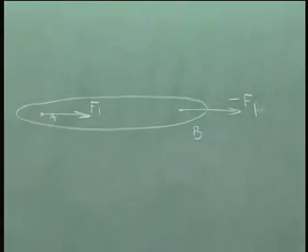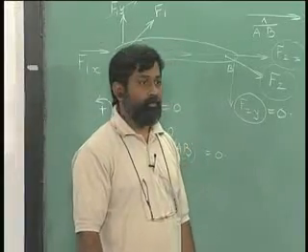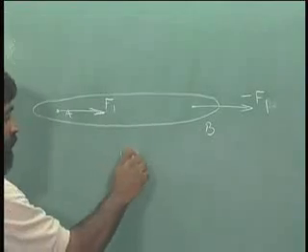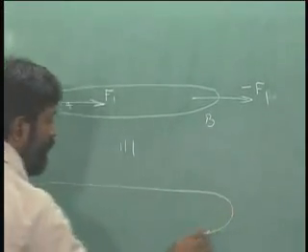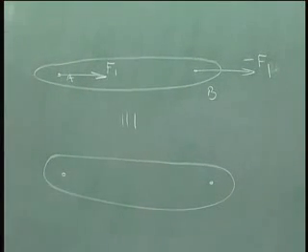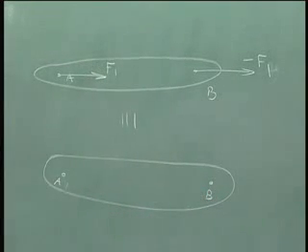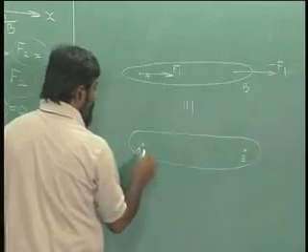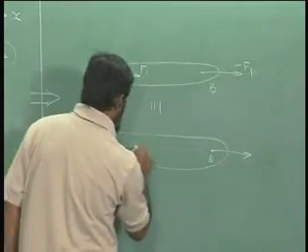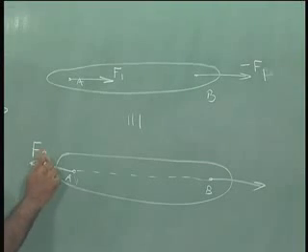Okay, I have used all the 3 equations in order to come up with this particular conclusion. If so, in other words, this is equivalent to saying that if I have a body where forces are acting only on two particular points A, B, then the force will act along that line AB, and let us call this as FAB.